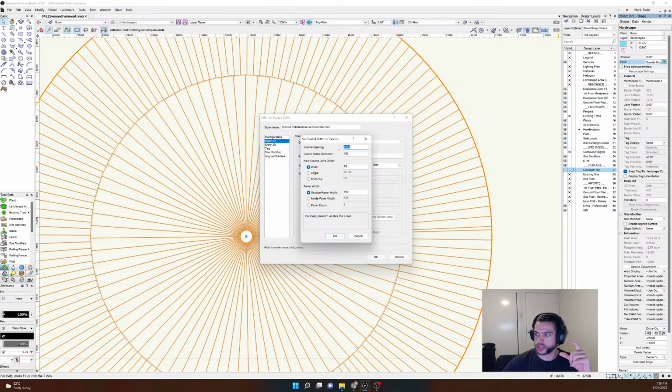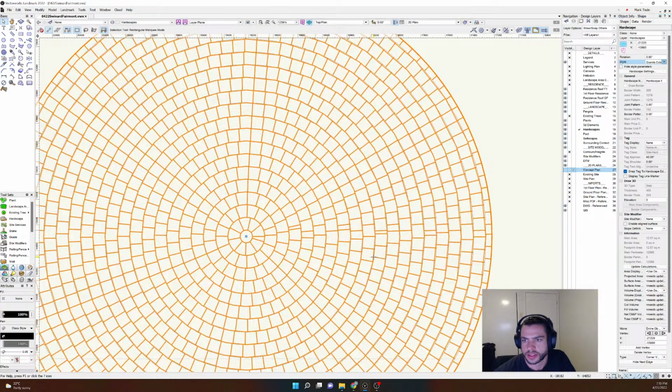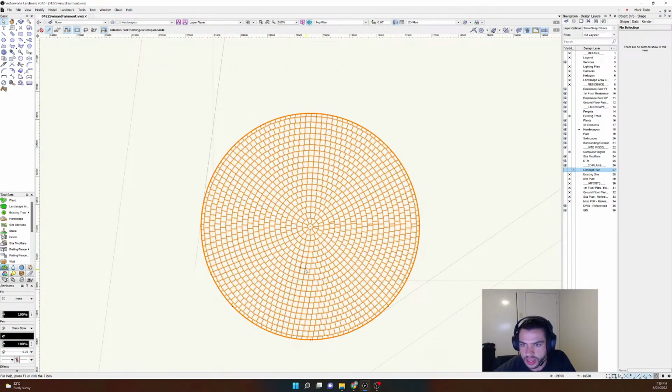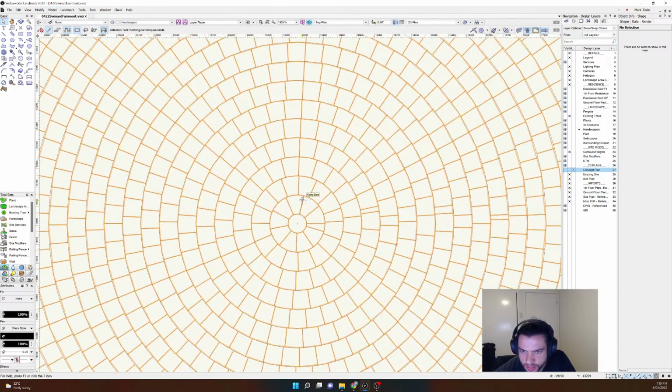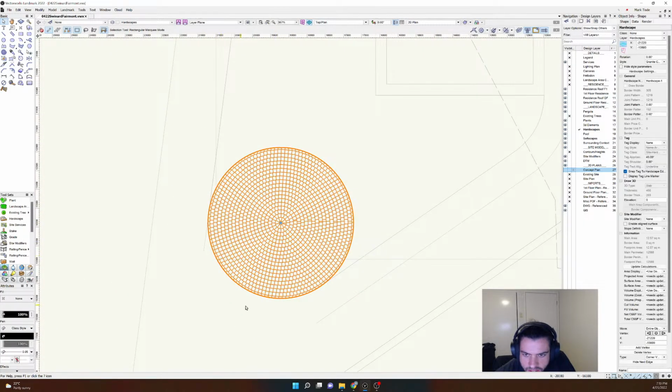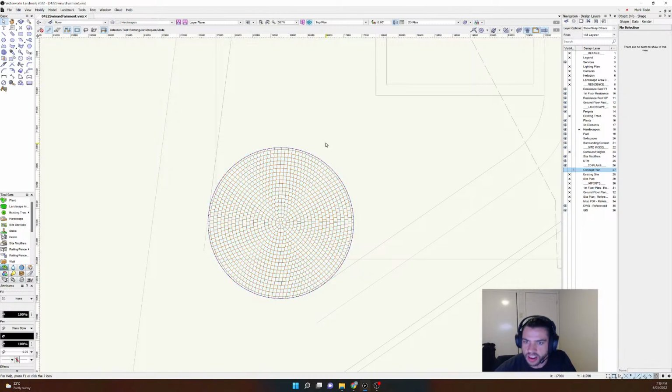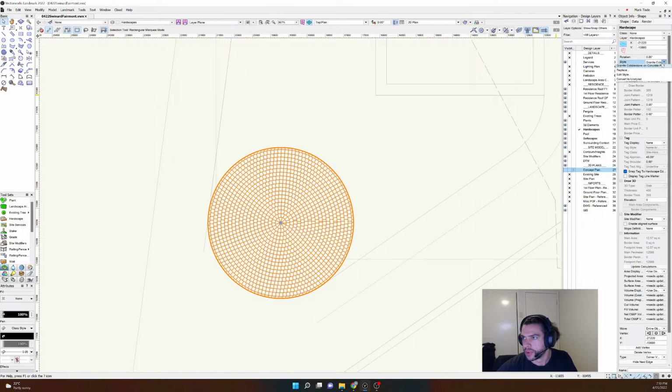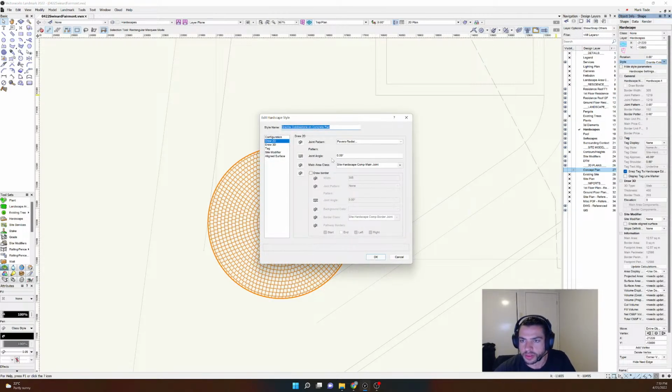So I want the course spacing to be 100 mil, I think, because the cobbles are 100 mil, or geez, I don't know how many inches that is. Maybe like 4 inches by 4 inches, or 100 millimeters by 100 millimeters. So I think if I change that course spacing to 100 millimeters, yeah, this is more what I want to see. Now you can see I've offset it by 50, but I don't really like that offsetting. See how the offsetting there? I don't know, it probably is fine. Like they're never gonna lay it exactly. But I might just play around with some of this.